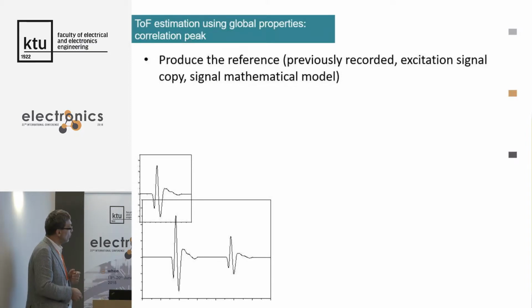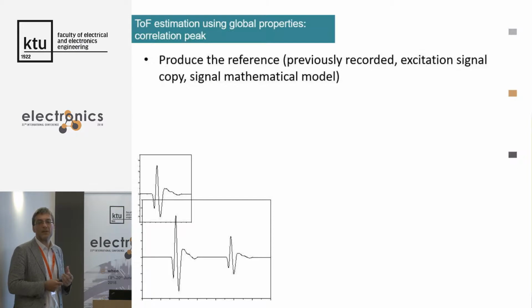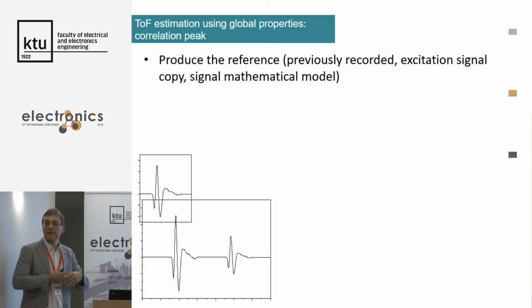So once you know what type of signal was transmitted, you are looking for the correlation. And correlation actually is a matched filter. You know that the narrower the filter that you use, the better the signal to noise ratio. The optimal filter is the one that matches the magnitude response of the signal.